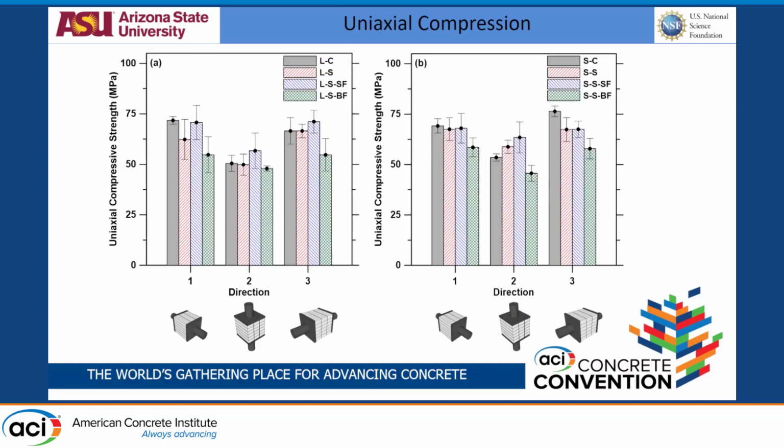So for this system, you did gain flexural strength, but what about compressive strength? Did you gain higher compressive strength, or did you remove anisotropy? To see that, we did a 3-directional test as I described before. What we observed is that in this system, the build-up direction was significantly weaker than the other 2 directions. Again, the thing that comes into the picture is the interfilament joints.